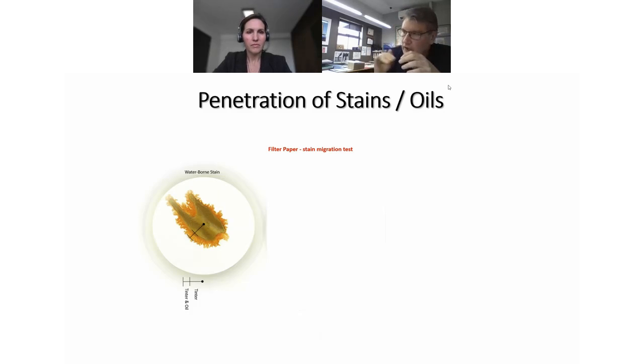And then you can see the orangey yellow stuff. That's actually the tint base, and those orange and yellow are little microscopic, what we call transmetal pigments, which help absorb ultraviolet, and ultraviolet is what damages the timber. I'll show you some photos shortly. And then right on the edge is some clear, and that's your oil. There's a little bit of oil in there, and so you can see that penetrates the most.